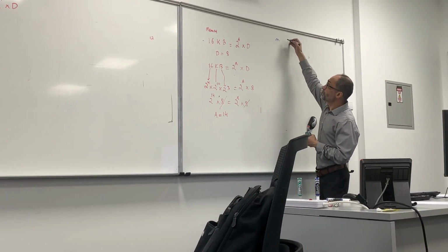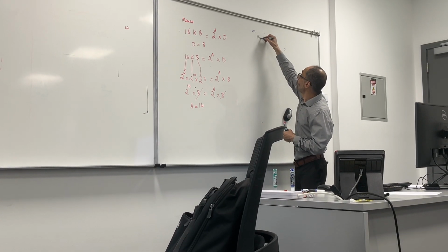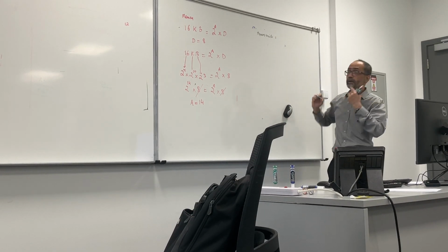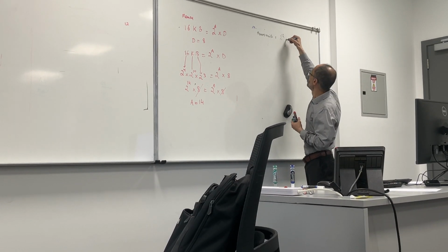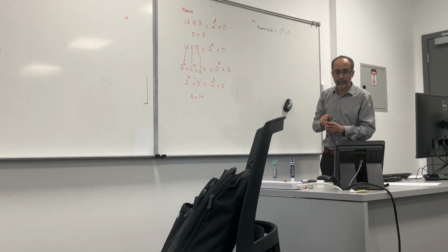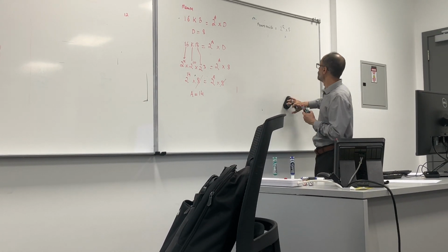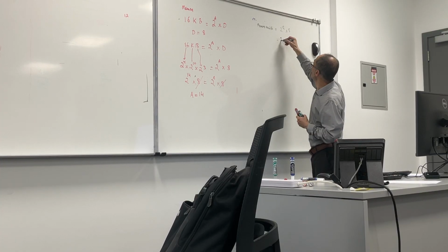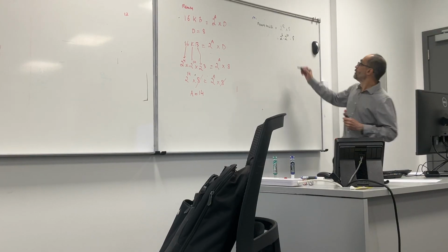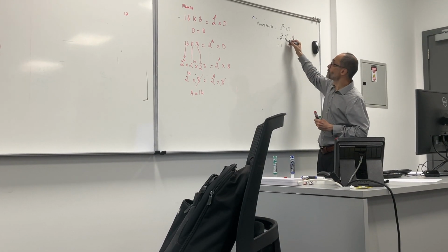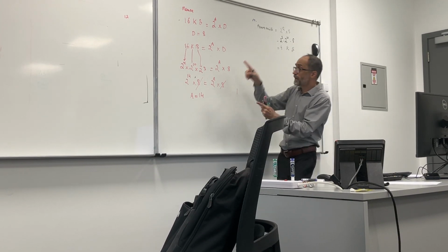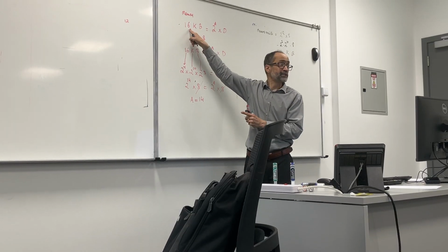Now the main memory or the memory available. What is the main memory available? It is actually 2 to the power 12 cross what? 8. If it is 2 to the power 12 cross 8, can we do it like this? 2 to the power 2 dot 2 to the power 10 dot 8. What is 2 to the power 2? 4. What is 2 to the power 10? Kilo. The main memory requirement of the processor is 16 kilobyte.